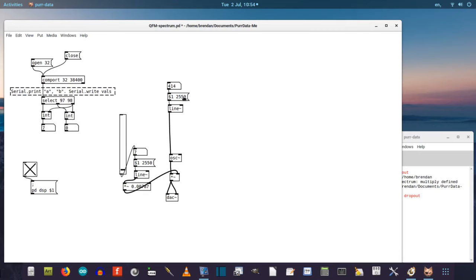And I need to change those two values, the 2.5 seconds, back down to 50 milliseconds. There we go. Happy days. So we have a center frequency for our sine wave oscillator, and we have an overall output amplitude control. And we discovered that we can modulate this frequency value to create vibrato. So we need a plus tilde object.